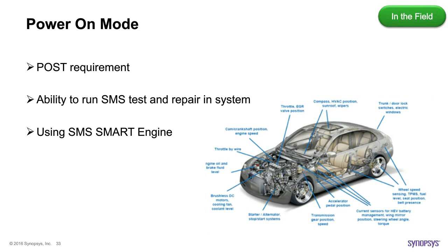And power-on self-test is a requirement these days. It's called POST. It's a requirement of ISO 26262 to ensure that the chip can test itself when it's powered up.